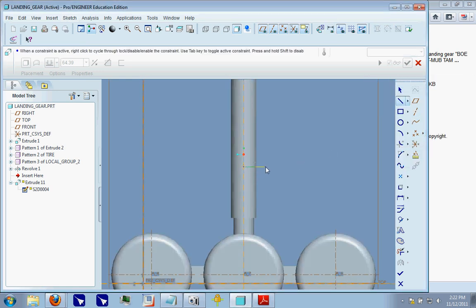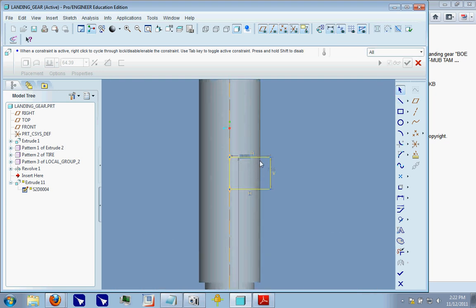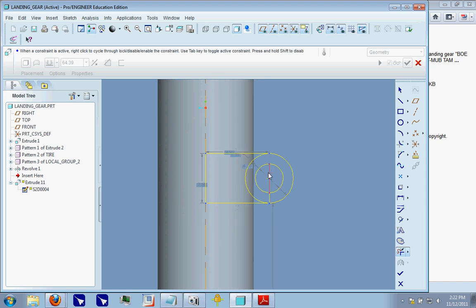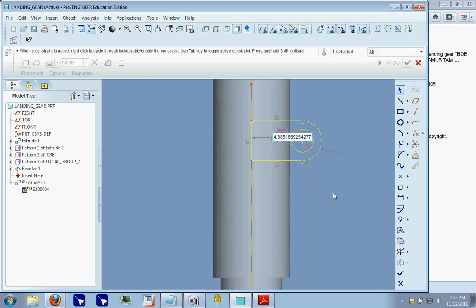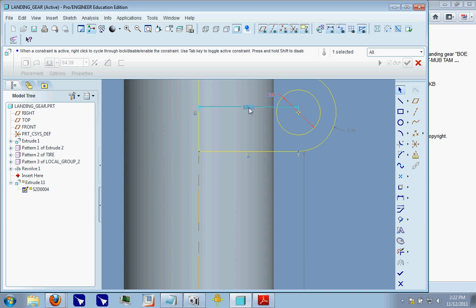Now the reason why I'm going from the center out is because when you actually go and make this, you don't want to have the extrude edges peeking out of the side where you wouldn't normally see them. So this just makes it a little bit easier. Alright, so we're going to cut that, and that, and that, and that. So there's just a really simple connection right there. I'm not putting a whole lot of detail into this like you might want to put in. And we'll make this 12 inches to get it out a little bit farther.